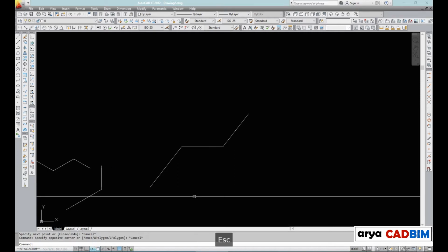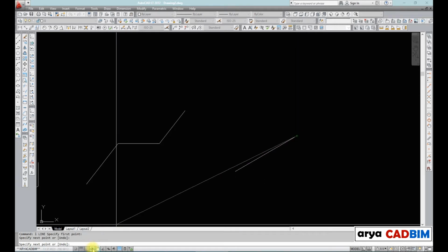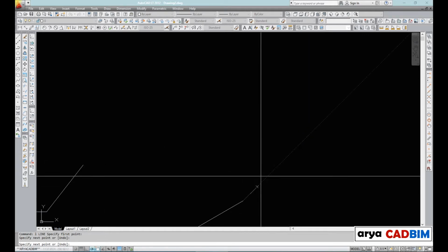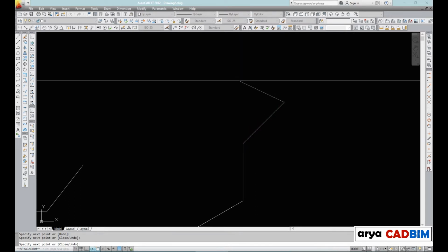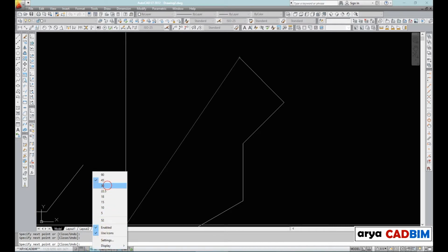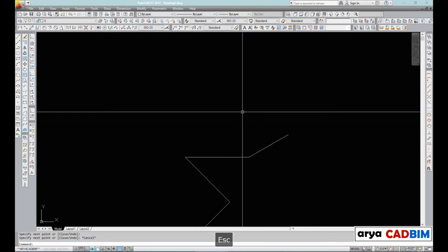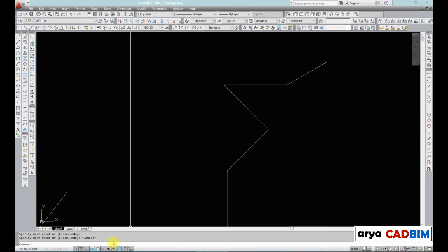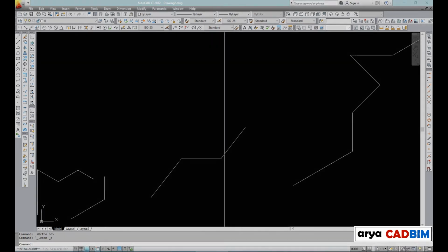You can also change the angle while you are drawing. You can start a set of lines, let's say with 30-degree angle, and without exiting the line command, you can change it to 45 for example. That gives you flexibility to draw any angle and distance that you want. Before we finish, remember when ortho mode goes on, polar mode automatically goes off. You can't have both turned on. And that's enough for F10 key, I think.